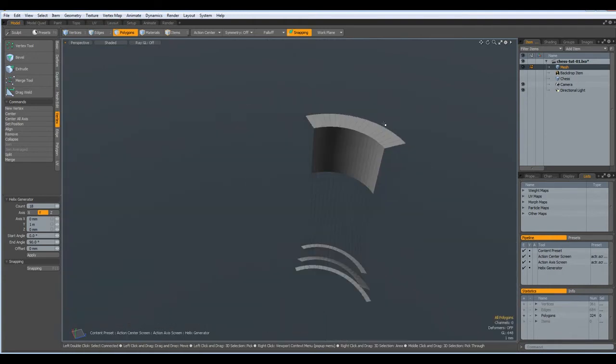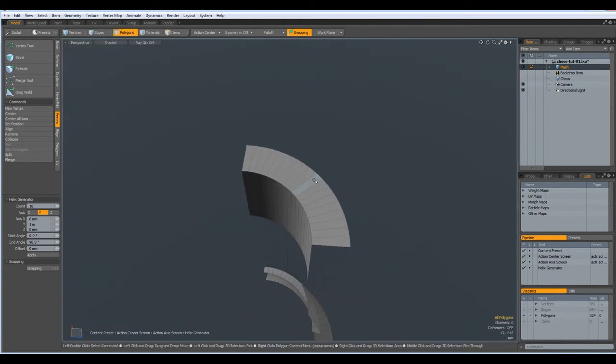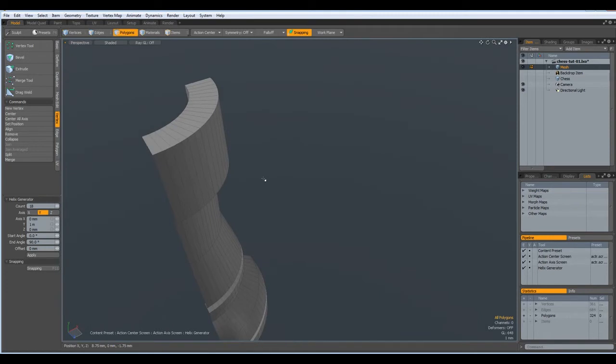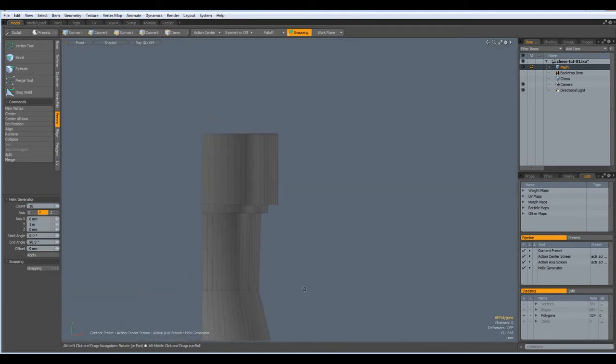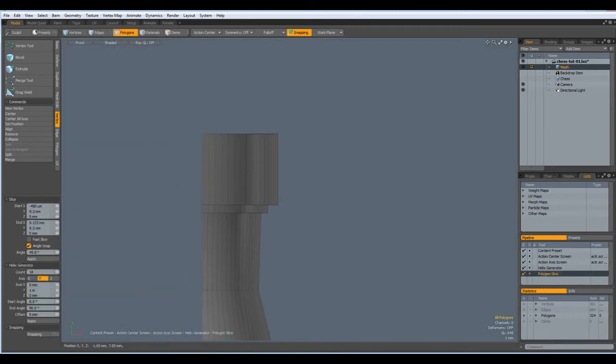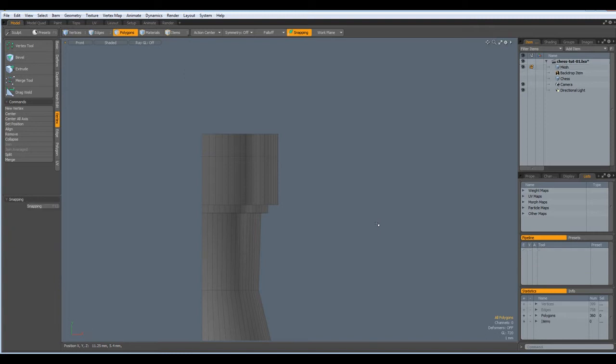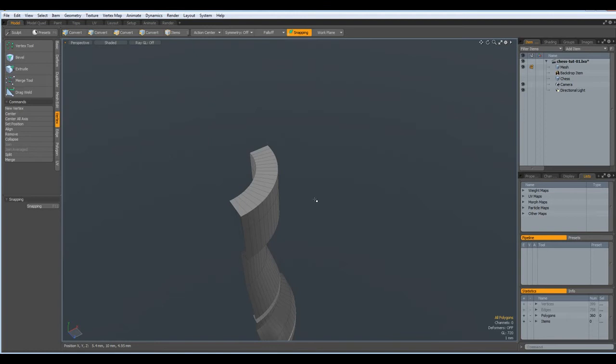First we need a cut through here, Shift C, cut through here, drop the tool, and now I can go to perspective, select 2, 4, 5, yeah, 5 is good, Shift up arrow, delete.